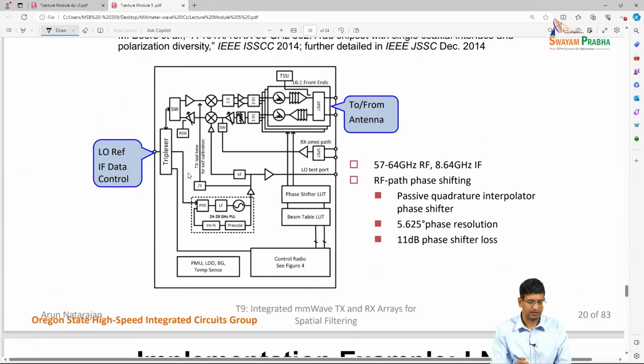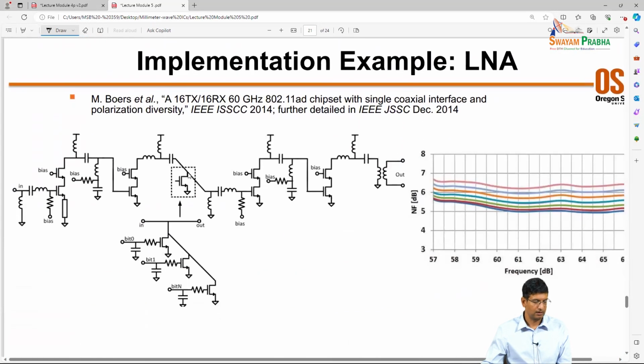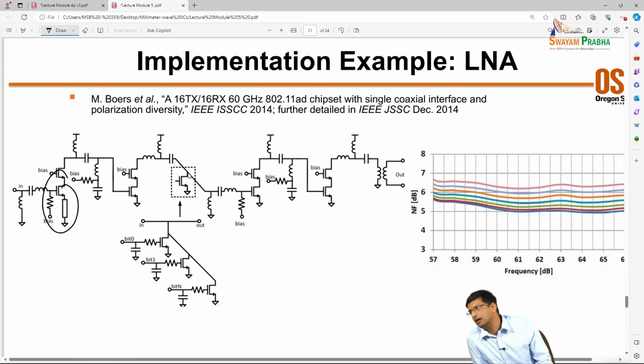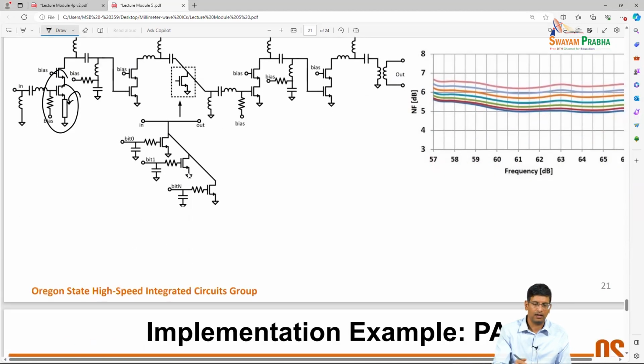If we look at the circuits themselves, we see again similar choices. For example, what you see here is an LNA with source degeneration, but this time instead of implementing it with an inductor, we implement it with a shorted transmission line because it can be modeled very well, and effectively, looking down, what we saw is just an inductor. So you can build source degeneration with that, and then you get to the output and you start transformer coupling.